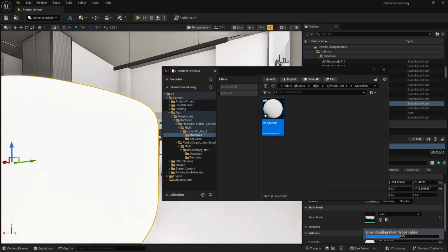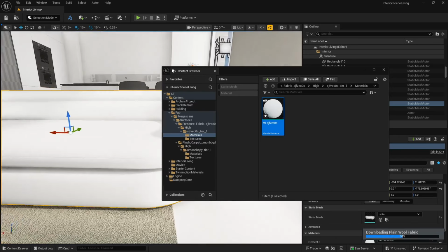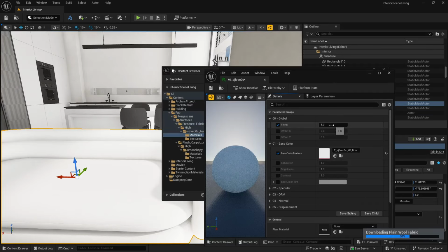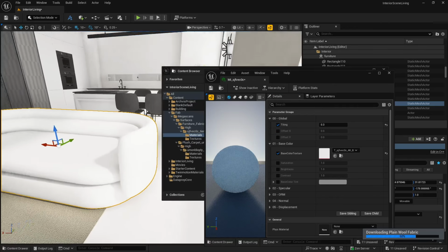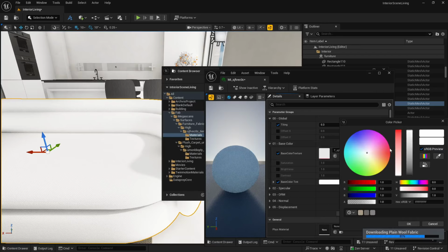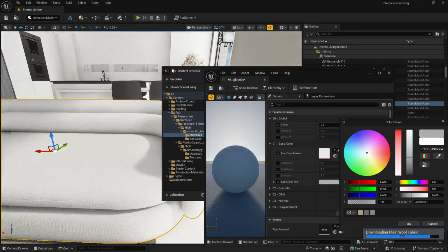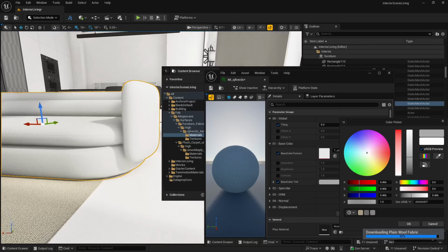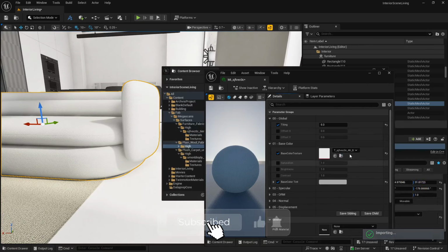And you can see, yeah, this is looking good actually. And you can play with the tiling. So let's double click it here, and let's do the tiling of 0.3 and check. So yeah, now you can see the material. This is how it is going to look, and maybe I can just have a base tint of somewhat grayish color. Yeah, so something like this. So you can see the result. This is looking perfectly fine with the tiling as well. So let's press the OK key.